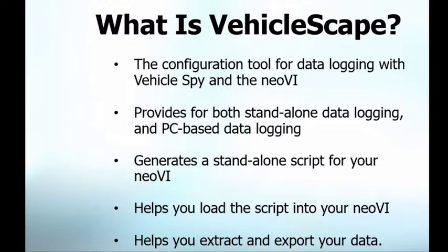And then essentially what happens, whether you're using it for PC or neoVI, is once you've picked all your setup, there's a big button on the bottom that says generate, and that generates in the background a bunch of function block scripts and received messages in the messages editor. So it's doing all of that for you. It then opens up our compiler, it compiles it, and if you are with your neoVI and connected over USB, you hit send and it sends it right down to the hardware. If you're using one of our wireless devices, you essentially just save the configuration that it made, and then you go to the website and upload it.